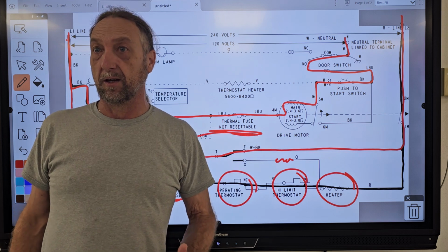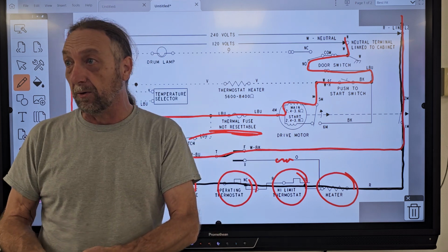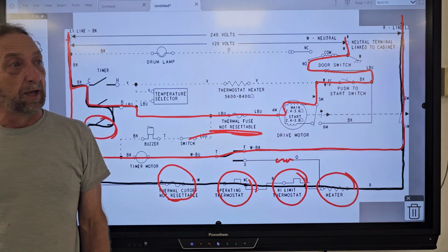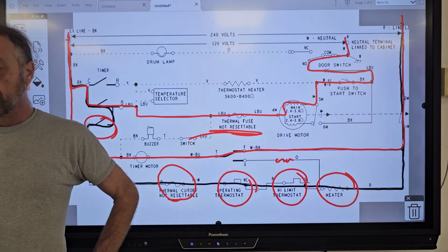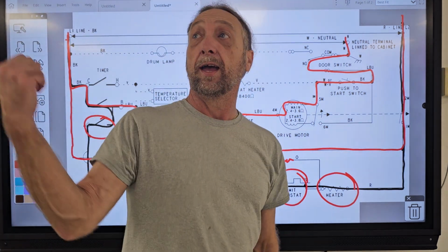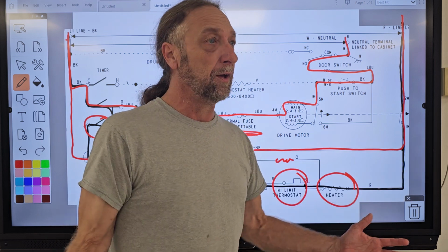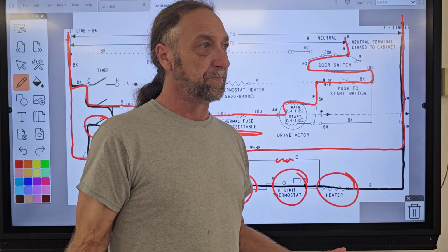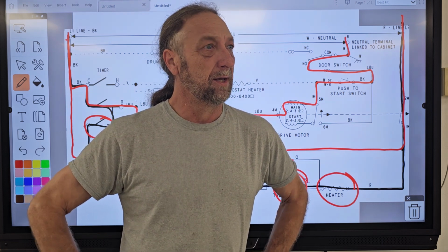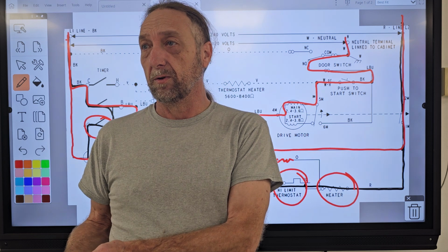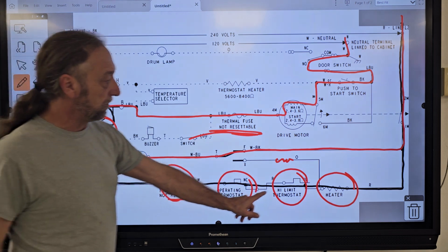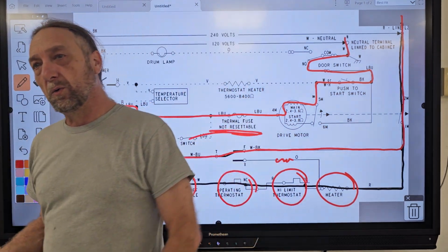That is a test. Just because you're not taking tools out or meter out to do that, that is your test. And if a judge sees you go right to the thermal fuse and you walk up to the machine and say, oh, it's either the door switch or thermal fuse, I open the door, click, click, go back to the machine, take the back off, check the fuse. Yeah, Judge, I found the problem. It's bad thermal fuse. You know, you're 30 seconds into the competition. Some judges will be like, yeah, but did he really check it properly? He got lucky and went right to that first part.